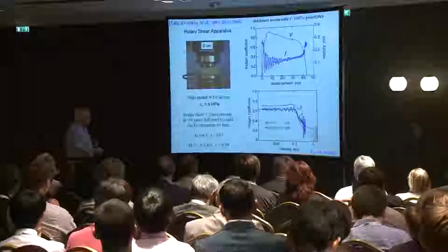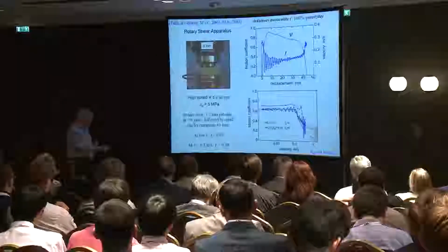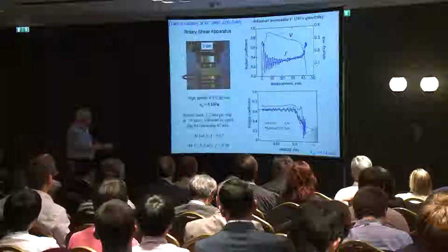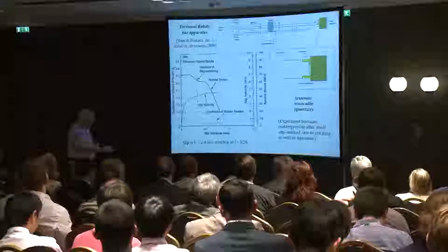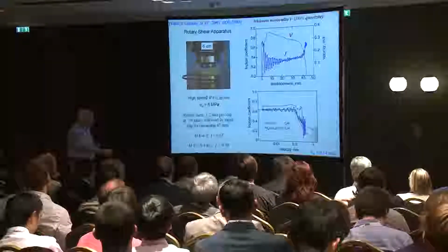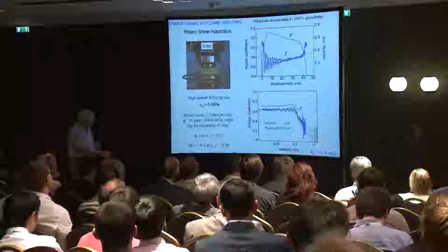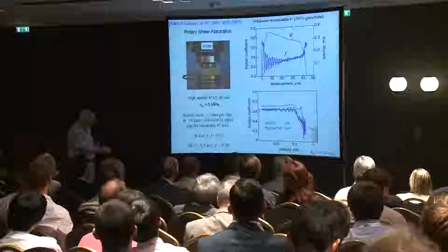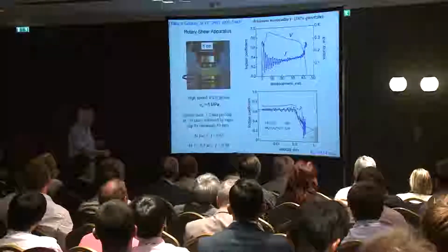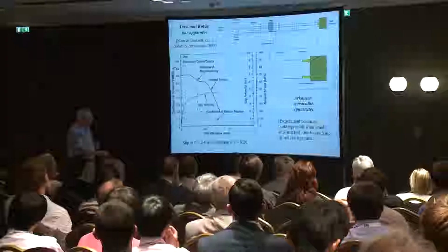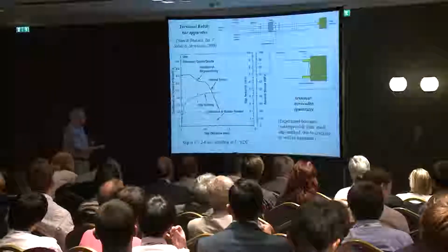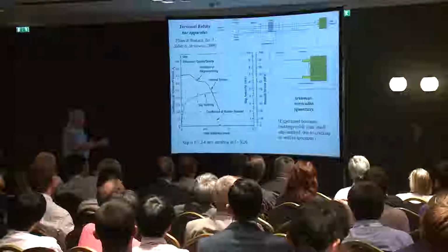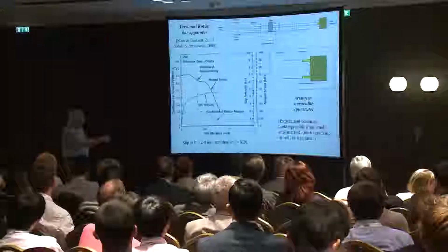And what these experiments show is before you get up to 1 meter a second in slip speed, you do have weakening. So here's the friction coefficient, and it weakens. The theory is these black curves, and the experiments are quite scattered. There's a lot of ringing in that apparatus, but there was also a very elegant experiment done with a so-called torsional Kolsky bar, where you take a rod and you push it into a contact.